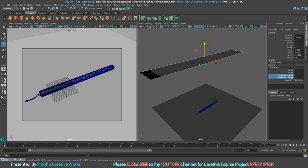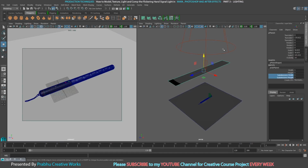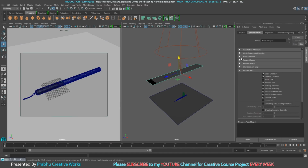So now I didn't want any cast or receive shadow from this object, otherwise it will block our spotlight over here. So I will select this object, go to attributes and go poly shape 1, and disable this one in render stats, cast shadow and receive shadow. That means this object cannot cast any shadow or cannot